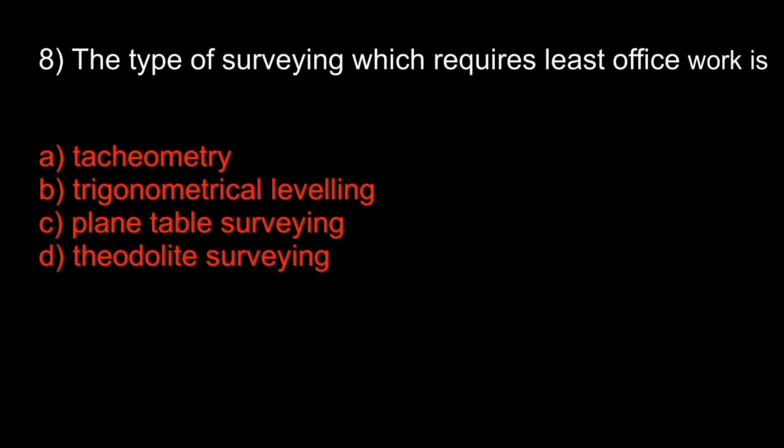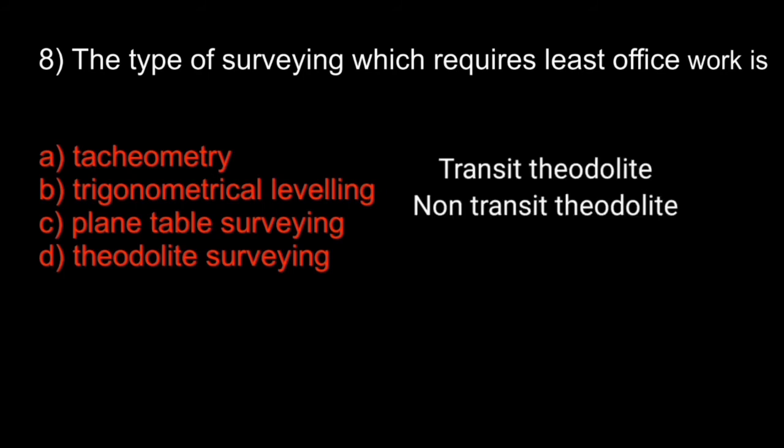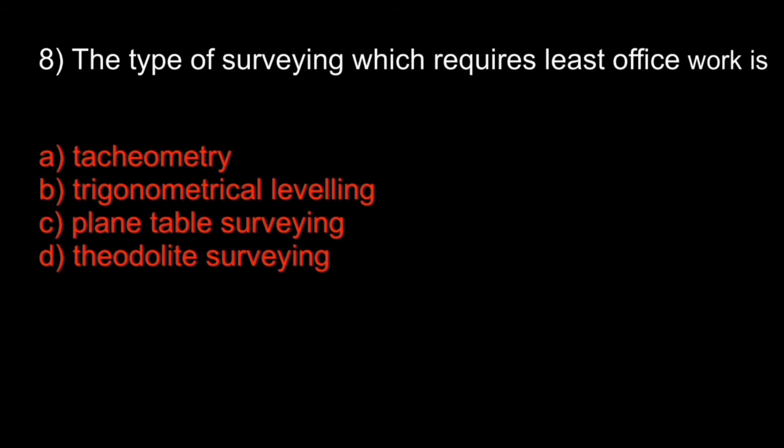Theodolites are primarily classified as transit and non-transit theodolite. If the telescope of a theodolite can be revolved through a complete revolution about its horizontal axis in the vertical plane, it is called transit theodolite. If the telescope cannot be revolved through a complete revolution about its horizontal axis in the vertical plane, it is called a non-transit theodolite. Now let us check the parts of a transit theodolite.